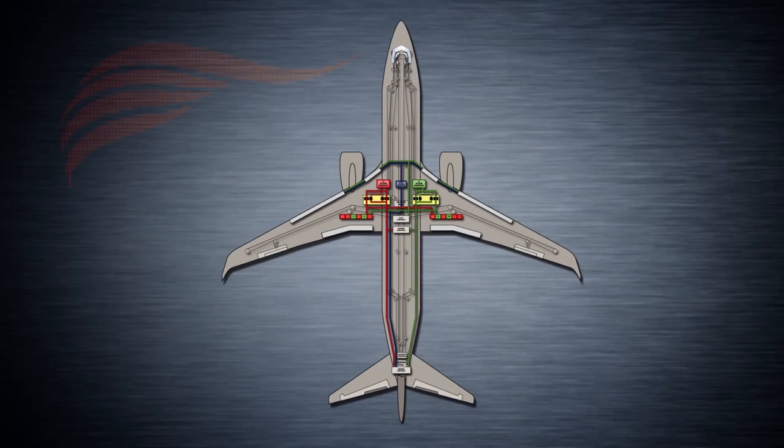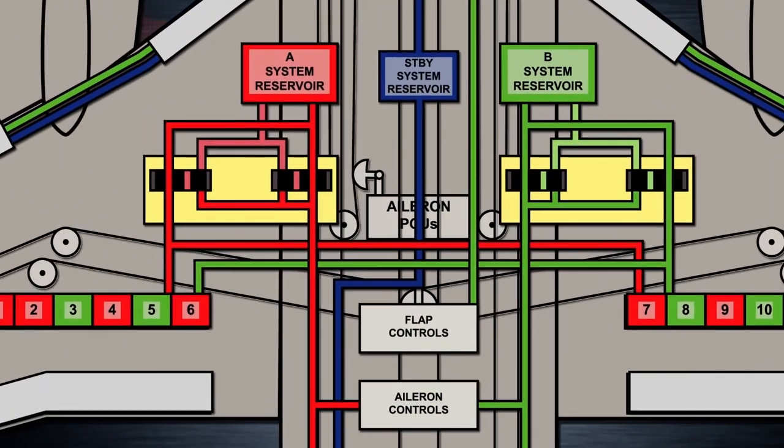During manual operation, the flight crew controls the roll attitude with control wheels that are interlinked mechanically in order to provide system redundancy. Just like with the elevators, the ailerons are actuated through pairs of cables that transmit force. Ailerons are also operated via the Aileron Power Control Unit, or PCU, that acts as an interface between the pilot's mechanical inputs and a series of hydraulic actuators that move the ailerons with wing cables. The aileron PCUs ensure that the ailerons are movable under any condition.